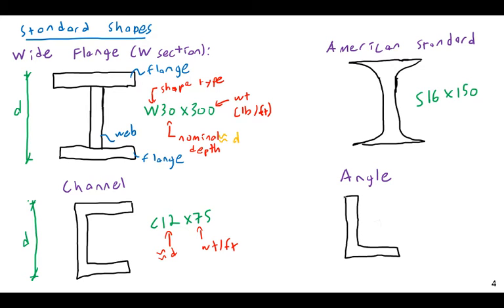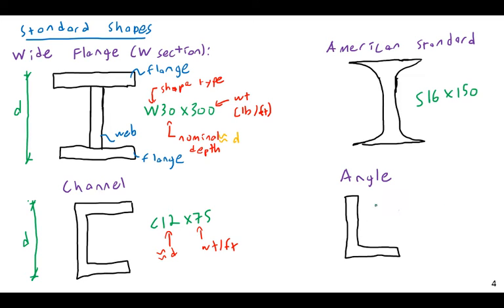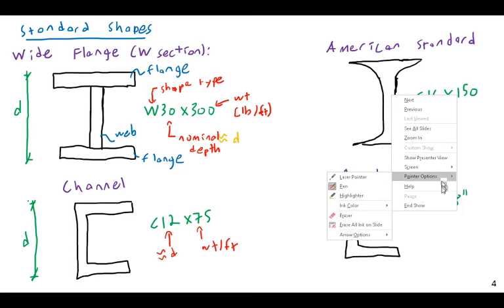And different shapes have different advantages, pluses and minuses. Some are better for bending, some are better for shear, some are better just for being cheap and light. It just depends on what you're building. So this one has a much different naming convention than the others. This would be something like L8 by 6 by 5/8 inch, because this actually is made of a bent plate.